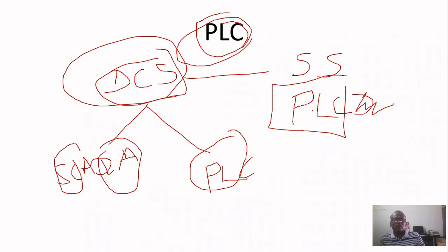Similarly, if you want to turn on a furnace, the furnace in NLC, Neyveli lignite, it is not coal, it is lignite. Inferior quality of coal is called lignite. The lignite is used to burn. That pulverized lignite you cannot burn directly if the furnace temperature is less than its burning temperature. That's why to ignite the lignite, the furnace will be started with crude oil initially.